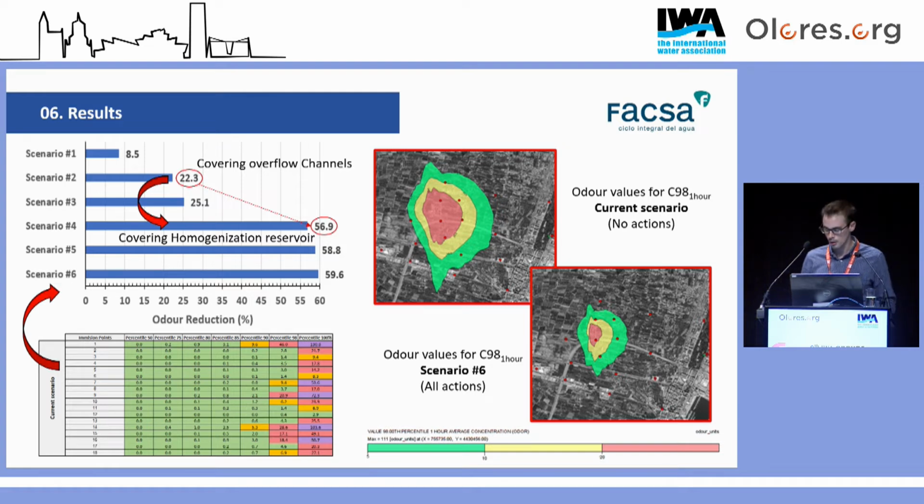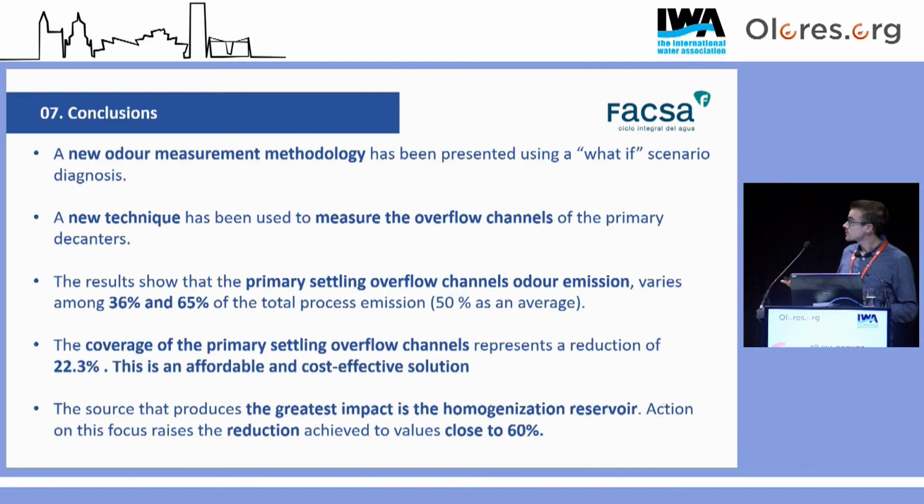So for this study, we concluded that we did a new measurement methodology in the sense that we use a what-if scenario. We don't use just one scenario, but a what-if scenario, several scenarios, and analyzing what happened in each scenario. We had to do a new technique or try to make something special in order to measure with the Lindvall hood in the overflow channel, which is not usual.